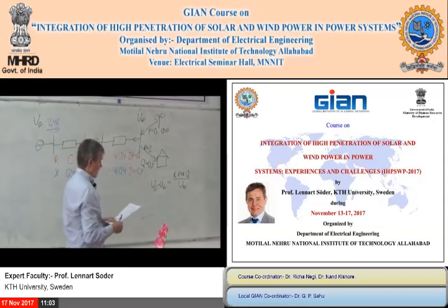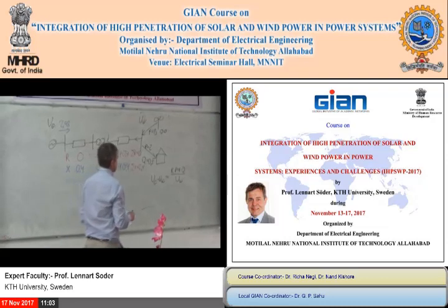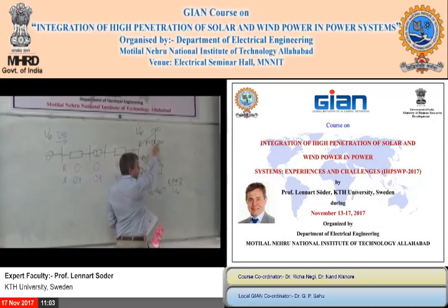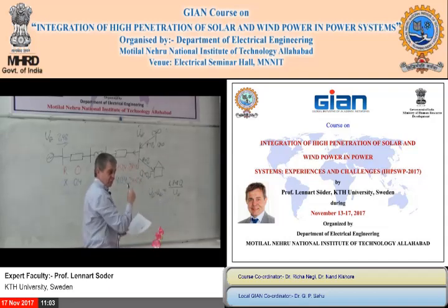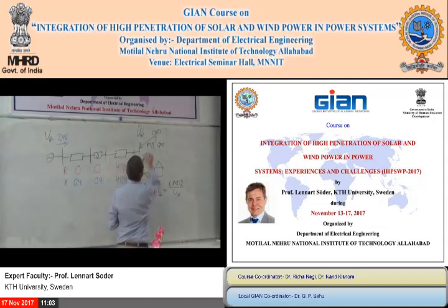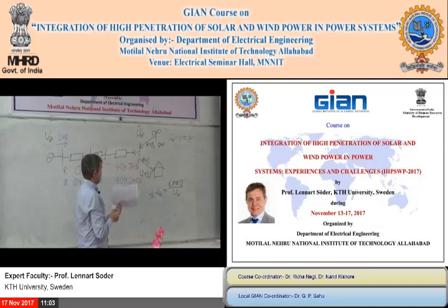In this case, this is not possible, because what you should do is consume more reactive power here, because the voltage is already 1.1. I used my small program to check, to make the calculations. The voltage is already here 1.102 per unit. And we have said that the voltage should be within plus minus 10%, so you should try to decrease the voltage here.